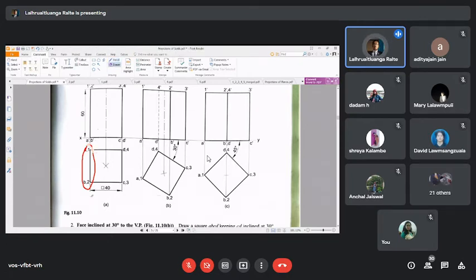So here it is directly the line. In this particular orientation, we have to address it as a line because in the top view, we are only seeing it as a line, right? Because our solid is standing. So this particular line represents the whole face that we are talking about, and it makes 90 degree to the vertical plane, which means it is perpendicular to the VP, and in this drawing, perpendicular to the XY line.